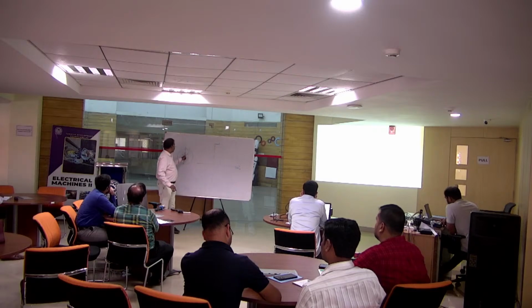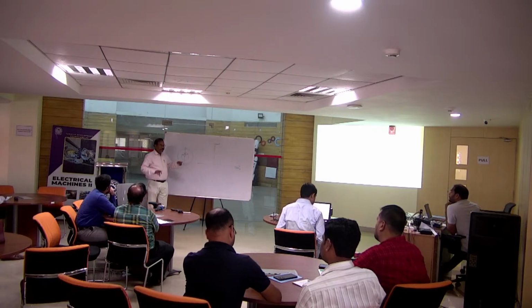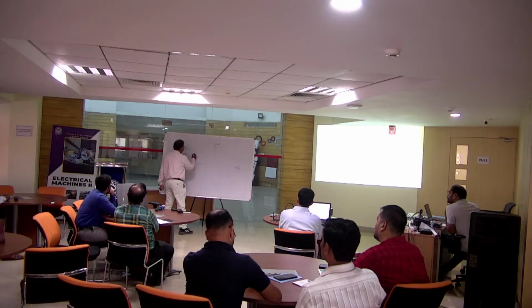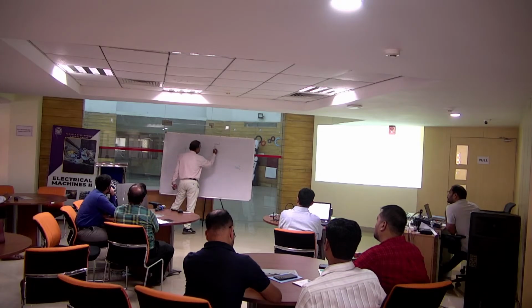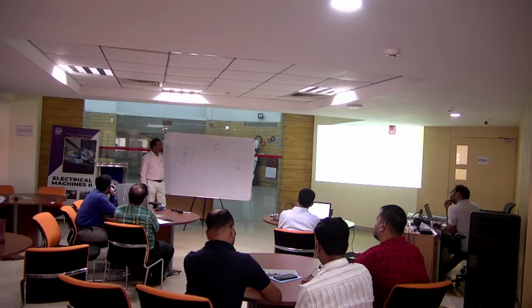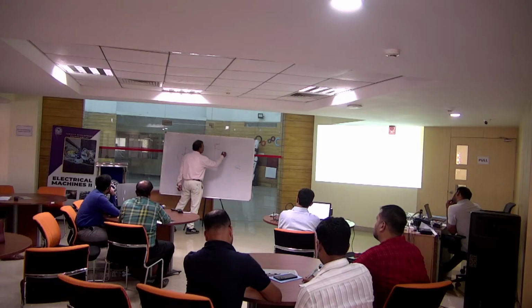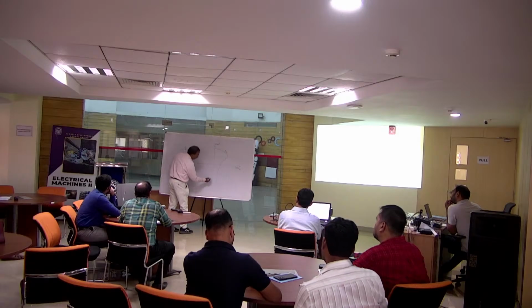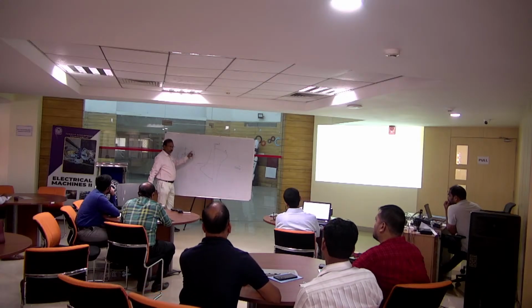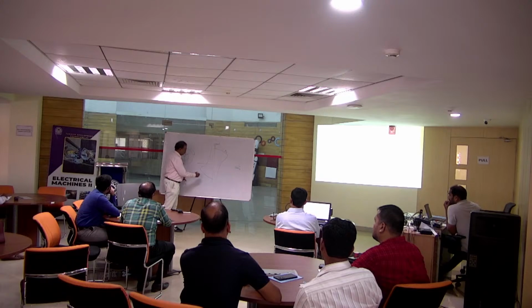Now, what we have seen, we have two magnetic fields rotating in opposite directions. For the one rotating in the forward direction, the torque versus speed graph will be like this. This is the speed torque characteristic due to the forward field, corresponding to forward flux. Now, for the reverse one, we have a graph like this. For the opposite rotating one, this is due to the backward field.